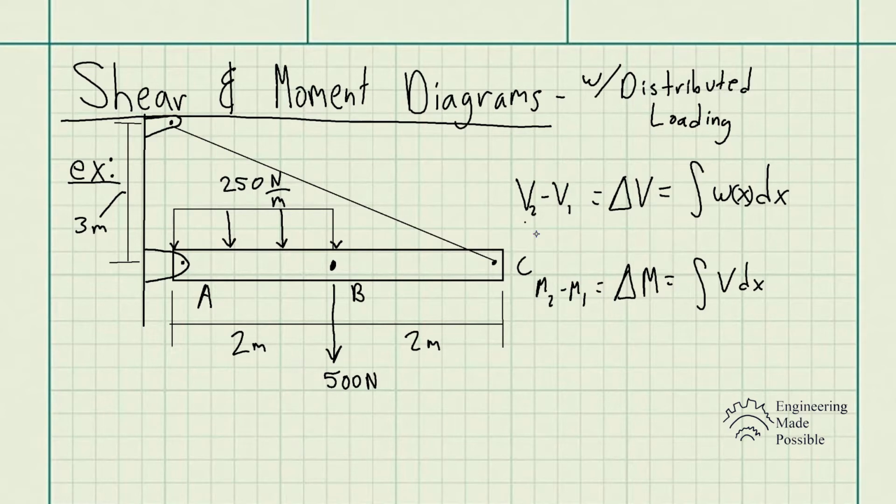And these are the equations we're going to be using to solve for the moments at point 2. So the first step, like always, since we have a distributed load, is to find your resultant force with the appropriate location of that resultant force. Remember x bar, going back to the previous video. Once you've found the resultant force and its location, you solve for the appropriate reactions. So we have a hinge here, with an x and y direction. Now for this cable, instead of trying to get the reaction forces, you basically just have a force along the cable, and let's call this FC.